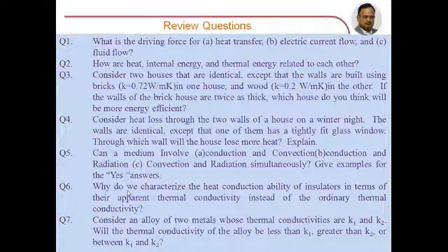Next, sixth question. Why do we characterize the heat conduction ability of insulators in terms of their apparent thermal conductivity instead of the ordinary thermal conductivity? Very interesting question. The answer for this is with reference to the poor thermal conductivity of air. Think in those directions, you will get the answer.